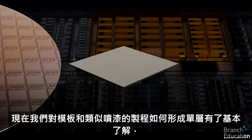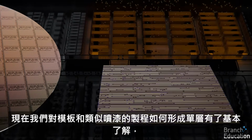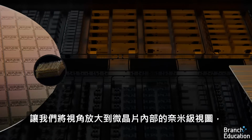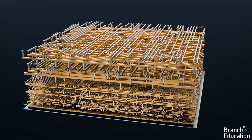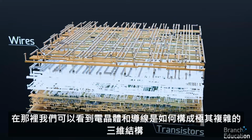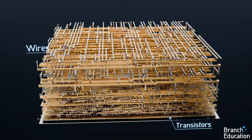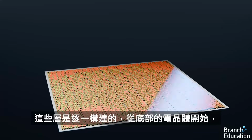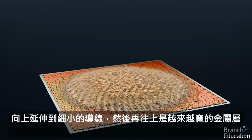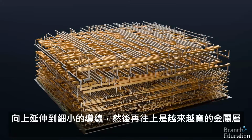Now that we have a basic understanding of how the stencil and spray paint-like processes form a single layer, let's zoom into a nanoscopic view inside a microchip, where we can see how the transistors and wires are incredibly complicated three-dimensional structures. Each of these layers are built one after the other, starting with the transistors at the bottom, moving up to the small wires, and then wider and wider metal layers further up.